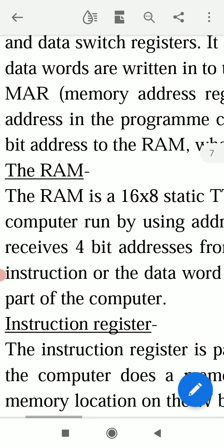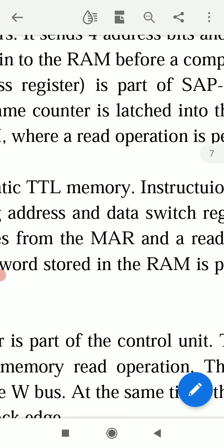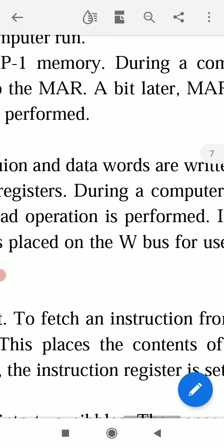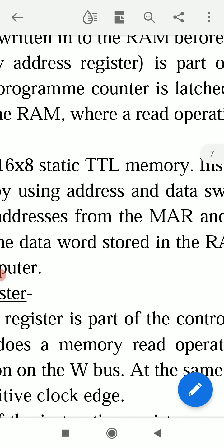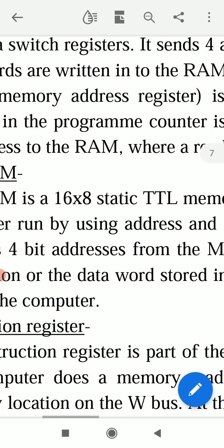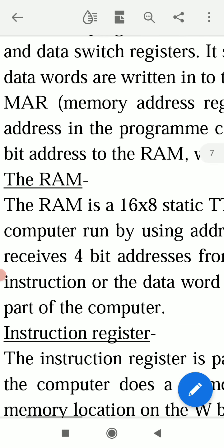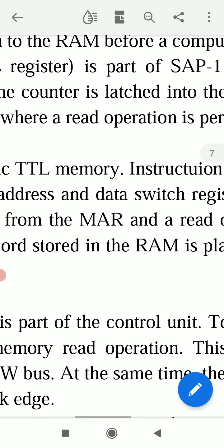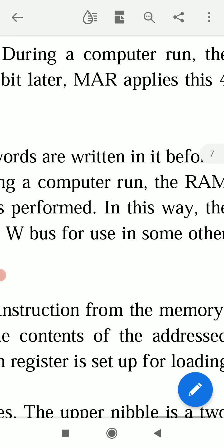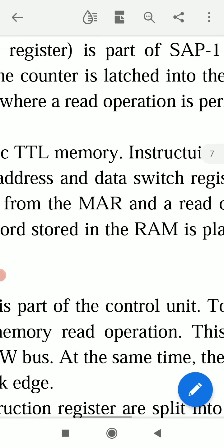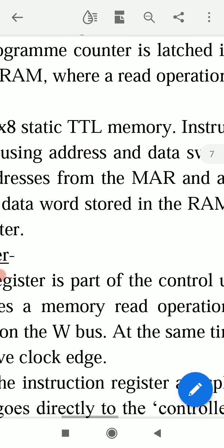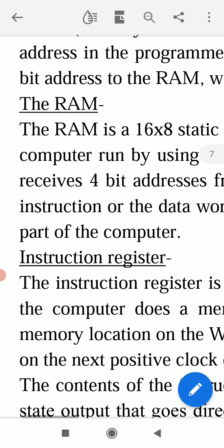MAR means memory address register. It is a part of SAP-1 memory. During a computer run, the address in the program counter is latched into the MAR. A bit later, MAR applies this 4-bit address to the RAM, where a read operation is performed.